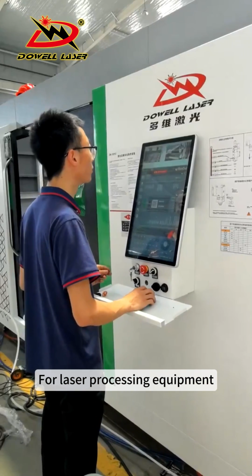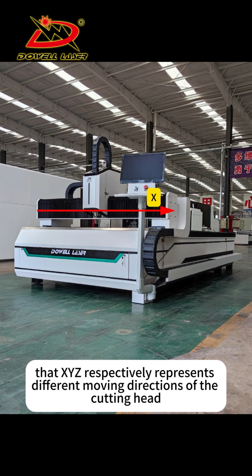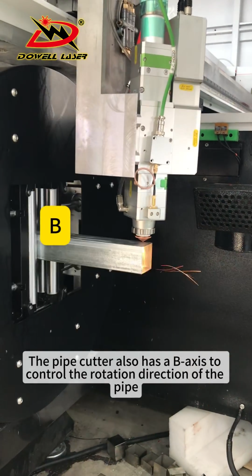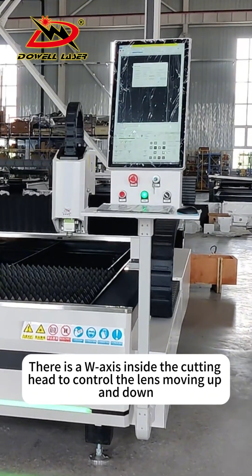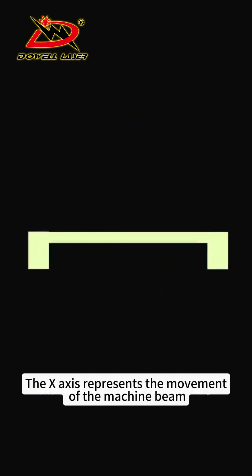For laser processing equipment, XYZ respectively represent different moving directions of the cutting head. These are the XYZ axes. The pipe cutter also has a B axis to control the rotation direction of the pipe. There is a W axis inside the cutting head to control the lens moving up and down. The X-axis represents the movement of the machine beam.